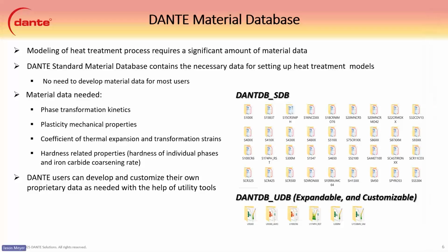What we could also do through the carbon model, if we have like a reheat or something like that, where the carbon would shift or move, we would model that at the end of the carburization process. So with the reheat, the time it takes to reheat and hold, we'll have additional diffusion and dissolution of carbides. We would do that in the carbon model, and then we would have that as a separate carbon profile going into quench compared to after carburization.